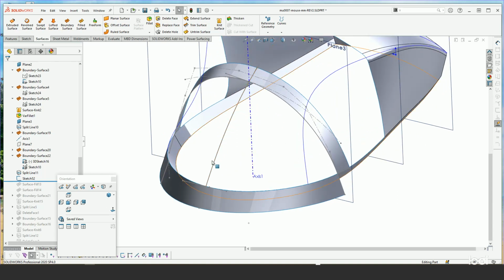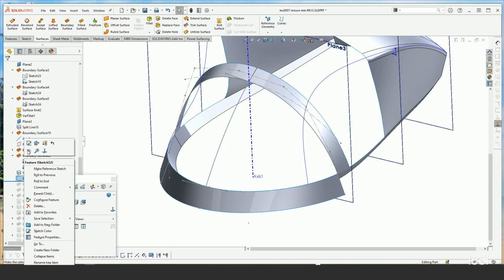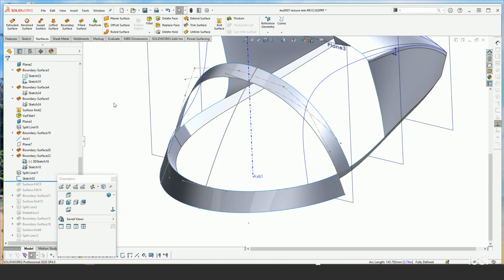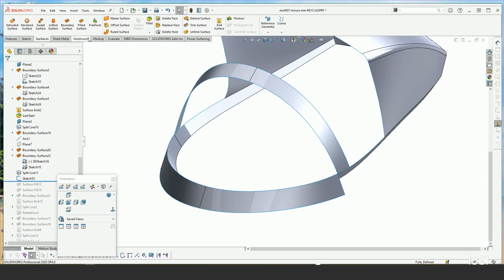Whenever you're doing constraint curves and fill, they can't extend beyond the actual fill surface itself, or they won't work correctly. So that's why I just had to basically, with this sketch, do a convert entity on this current existing sketch and then trim it back or pull back its point to here. So with that, we can go ahead and just try this.